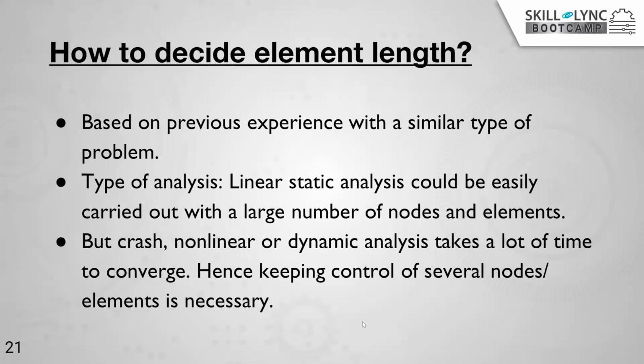Suppose you don't know, you can discuss with your teammates or seniors and understand what mesh size is being used for a similar problem. You can start with that. Or, depending upon the type of analysis: for linear analysis, you can mesh as fine as possible. But if it's a highly nonlinear analysis, which takes a lot of time, in that case you need to keep a balance between the number of nodes and the time taken for analysis.